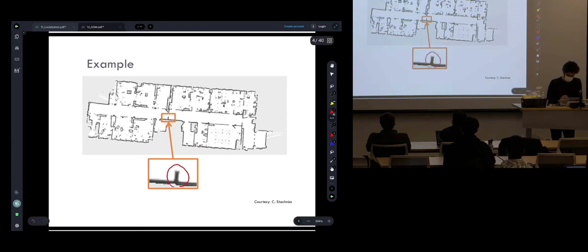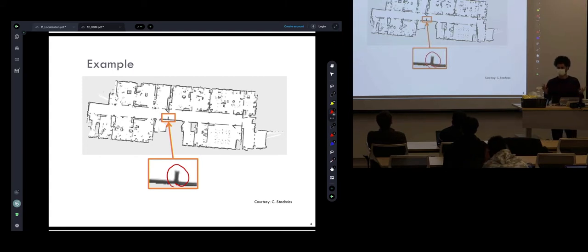As you can see, when you zoom in, once you build a map, because the grid structure is rigid and the resolution is fixed, there's no way you can increase this resolution. You're bound to this particular grid size. You used your data, the map inference is done, and you cannot increase or enhance the resolution. So this is built in, it's baked into the algorithm. It can be a problem or maybe not. You can still accomplish a lot of autonomy tasks using this map. But it is insufficient for general 3D scene understanding and tasks for today's applications that we have in mind.